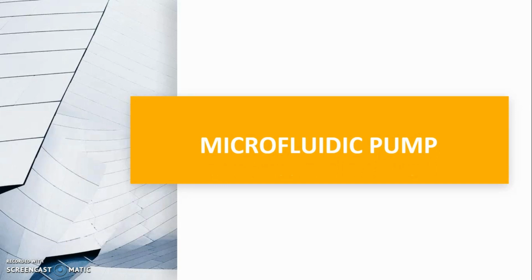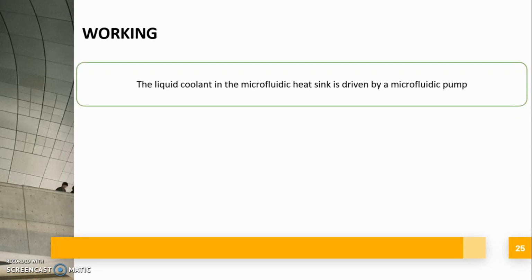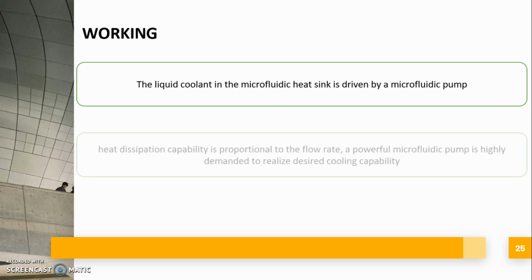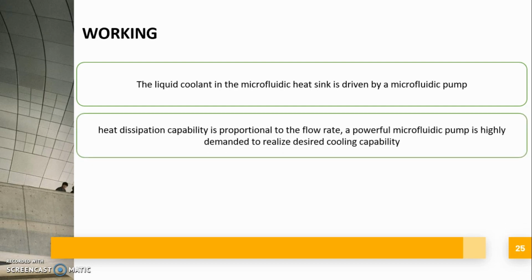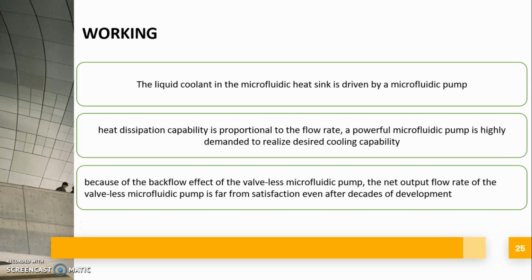Now let's talk about the microfluidic pump. The liquid coolant in the microfluidic heatsink is driven by the microfluidic pump. Since the heat dissipation capability is proportional to the flow rate, a powerful microfluidic pump is highly demanded to realize the desired cooling capability. Unfortunately, because of the backflow effect of the valveless microfluidic pump, the net output flow rate of the valveless microfluidic pump is far from satisfactory, even after decades of development.